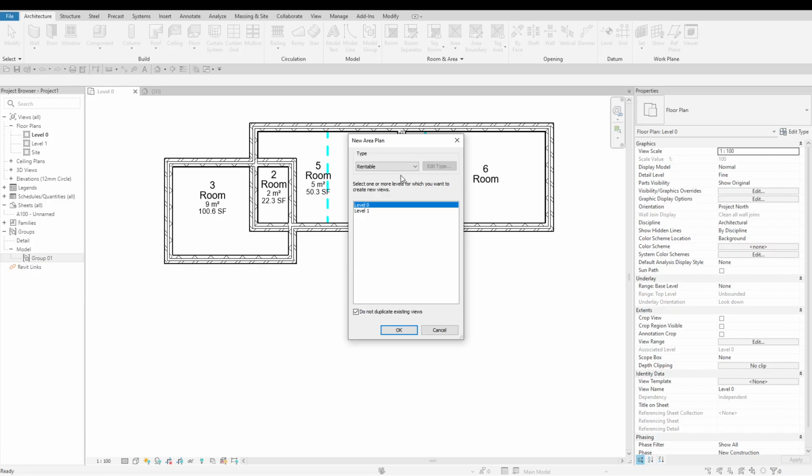Office area. This is the area where tenants typically house personnel, furniture, or both. Floor area includes spaces such as washrooms, janitorial closets, electrical rooms, telephone rooms, mechanical rooms, elevator lobbies, public corridors, and other areas used primarily by tenants on a particular floor. Major vertical penetration. This includes stairs, elevator shafts, flues, pipe shafts, vertical ducts, and their enclosing wall.